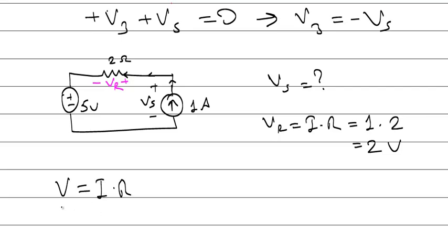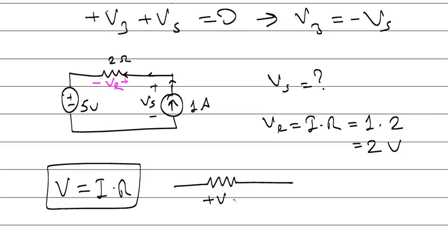Remember Ohm's law. Ohm's law gives the relationship between voltage and current of the resistor. It assumes the directions of voltage and current are like that. You have to declare the current entering from positive in order to use Ohm's law. Otherwise, it will not work. If you say the current is from negative to positive, Ohm's law will not work. It is wrong. So it's 2 volts.